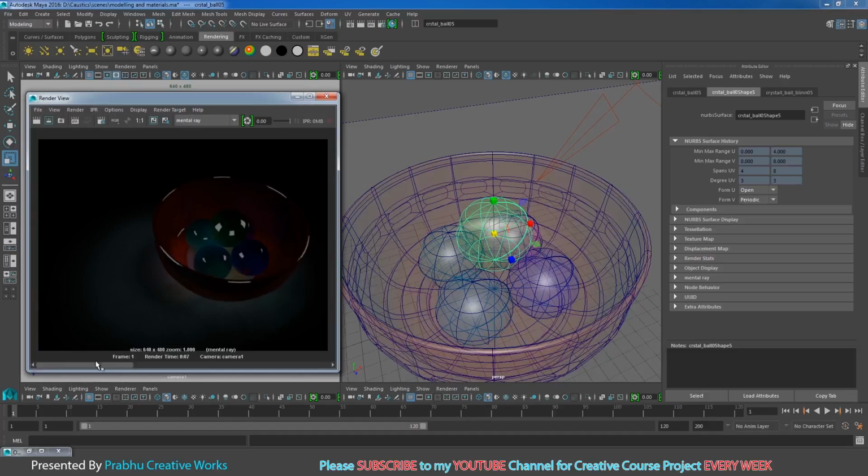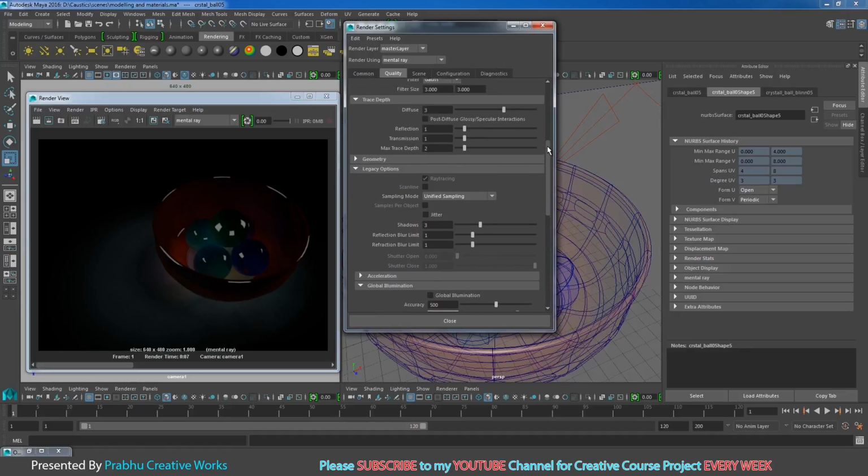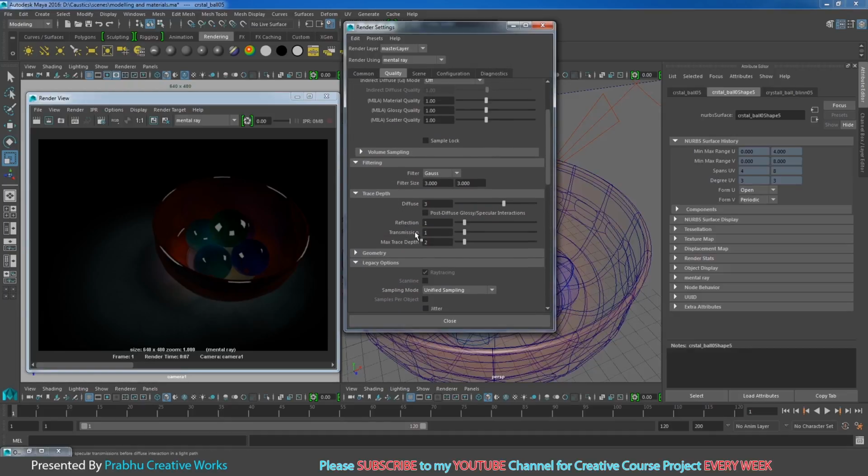So now you see our crystal cup will be colored, but you cannot see it clearly because we have stopped our color over here. Go to render settings. In the quality tab, you have the ray trace option, trace depth. We already set one reflection, one transmission and maximum trace depth, but it has a lot of thickness.